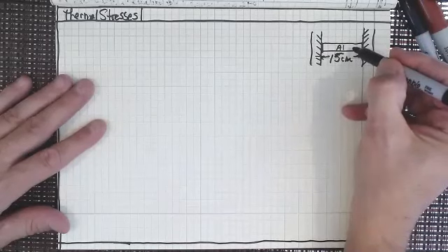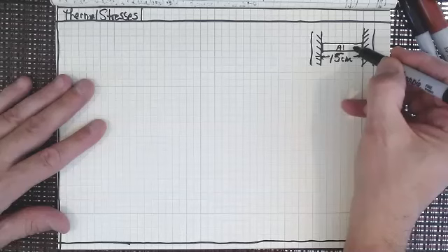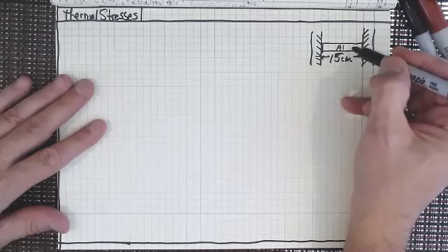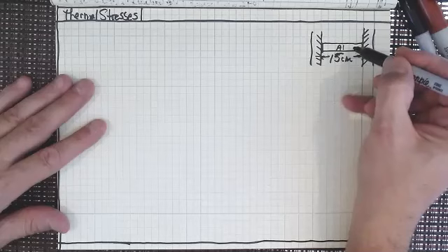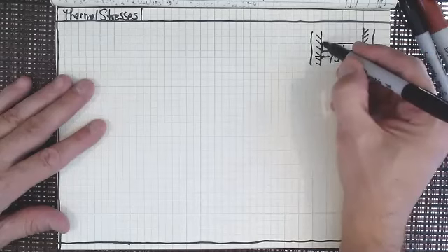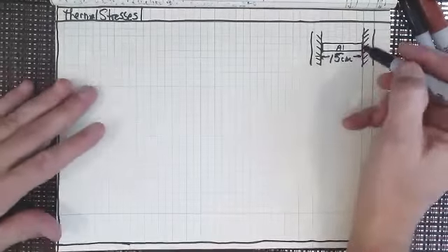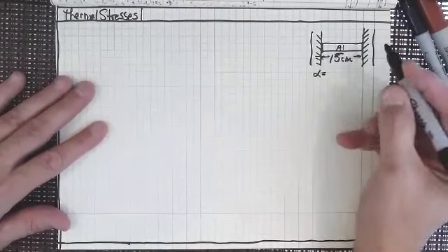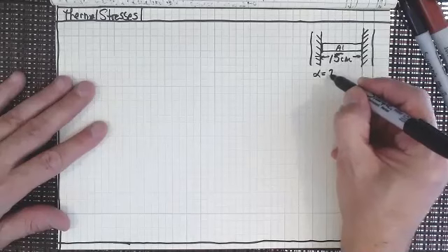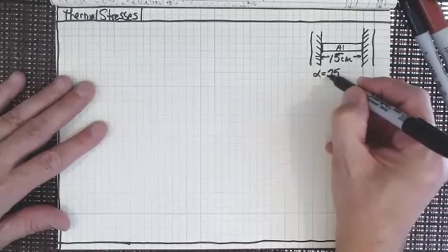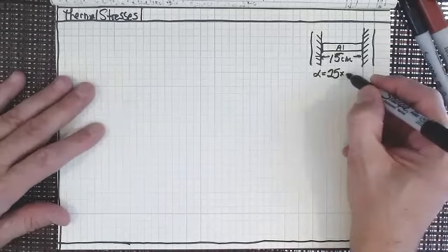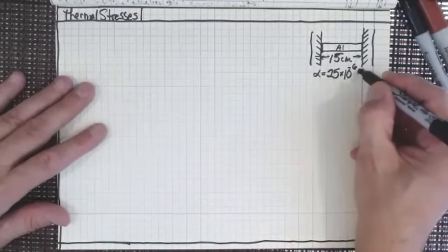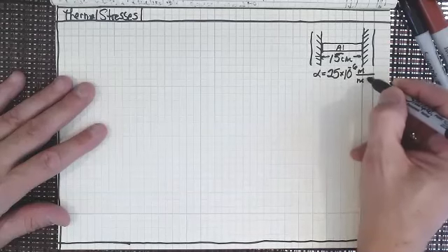And that's why you didn't take the steel bar back, right? Because the steel bar has half the thermal expansion coefficient of the aluminum bar. Or maybe it's not even an aluminum bar. Maybe it's something that has the same coefficient as aluminum, but is not steel. It's a ceramic. So you could get through the prison security system with the thing. Anyway, we're saying it's aluminum. And we also know that the aluminum coefficient of thermal expansion is going to be 25, and that is literally more than twice what steel is. 25 times 10 to the minus 6 meters per meter degree Celsius.